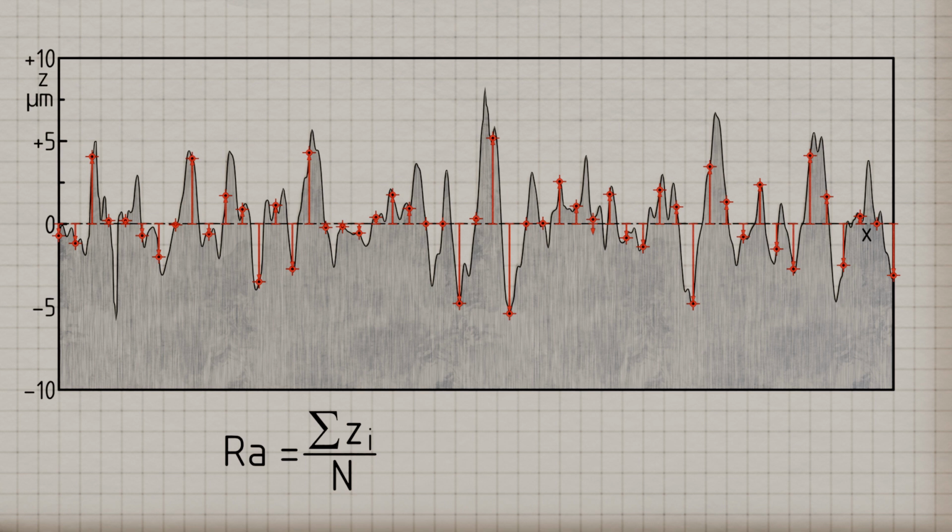According to the standard, this parameter is called the arithmetic mean height RA. The former term, according to the old standard, was average roughness value. In fact, to determine the RA value, the respective deviations would have to be recorded at infinitely many points along the roughness profile to ensure that every surface roughness along the entire profile is captured.